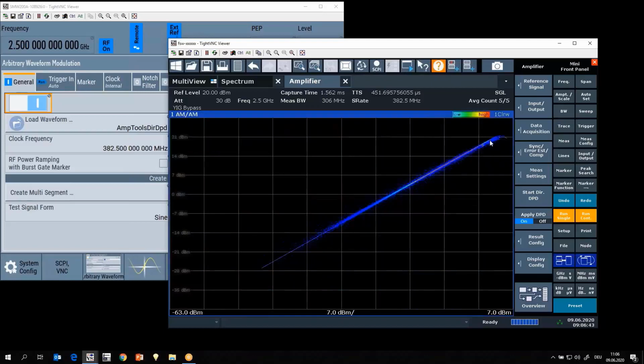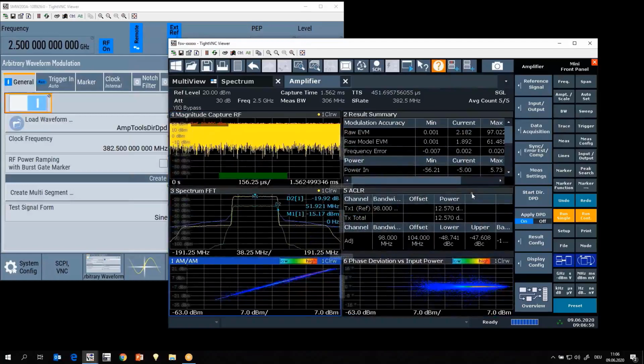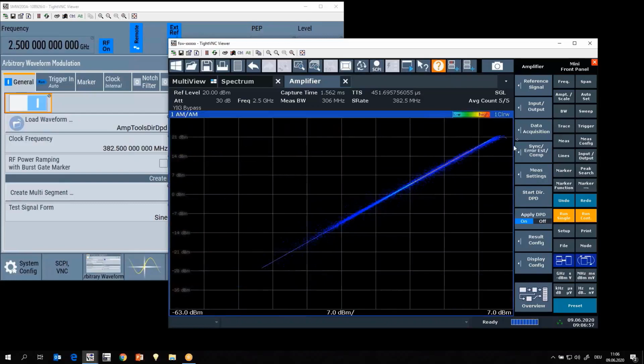Moving them down here in amplitude causes an EVM. But it's not a significant error, as typically we're talking only about a low percentage of points that lie up here. The majority, as you can see in the color indication, is down here. And since this area up here is all blue, we only changed a few samples.